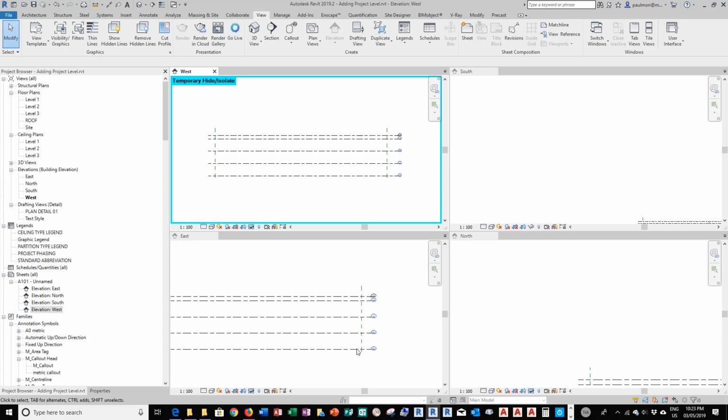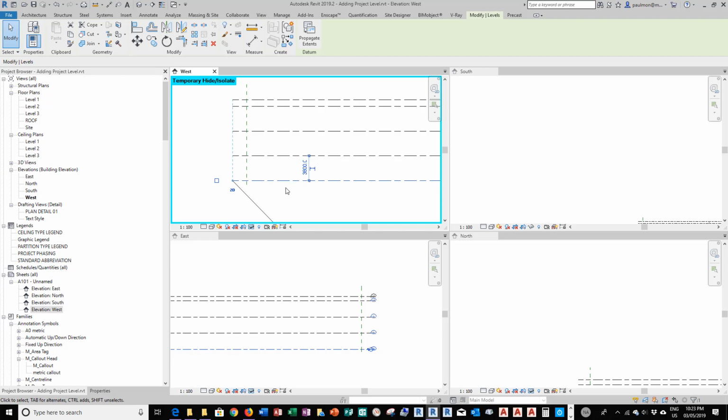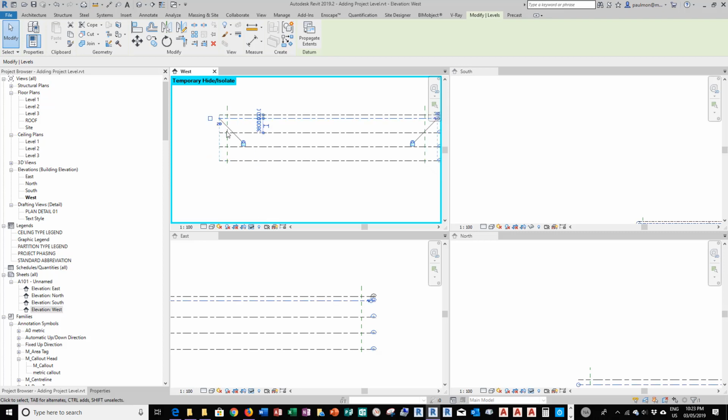So I adjusted it, fixed it, and then went back to the previous elevation and found that was messed up, until I understood that you really should turn the level datum line into 2D setting after you basically set it up to cover the range of the building. So we should just double check that once in a while. Make sure that nobody turns this level datum into 3D mode unless you really need to.